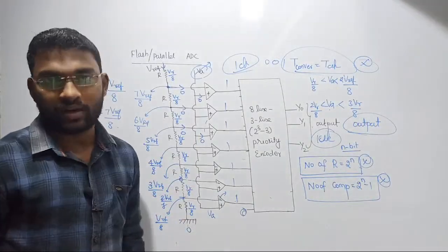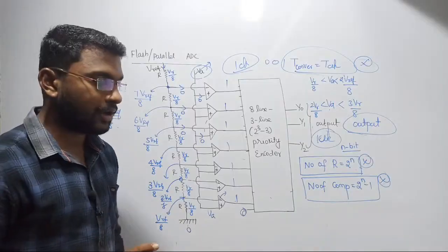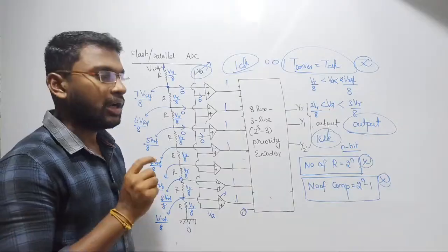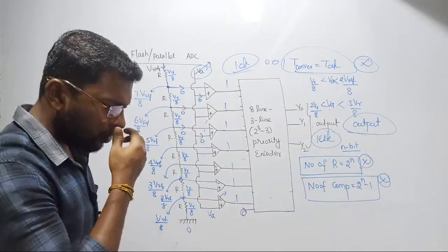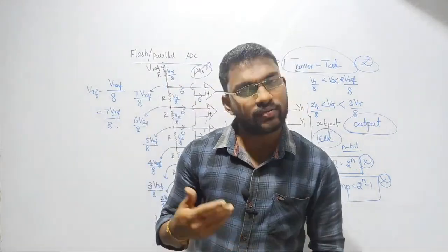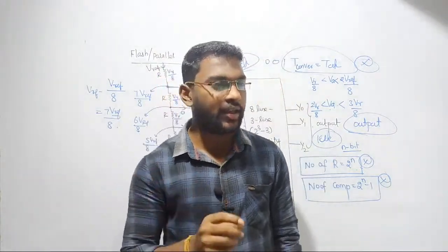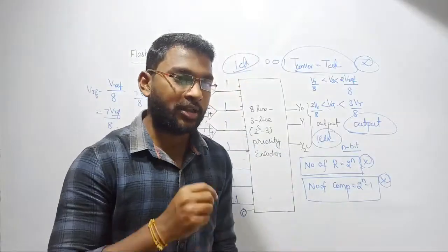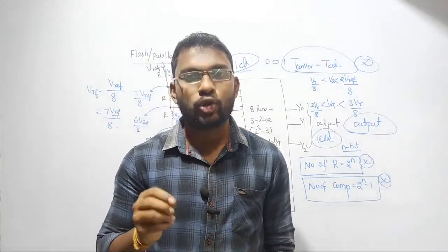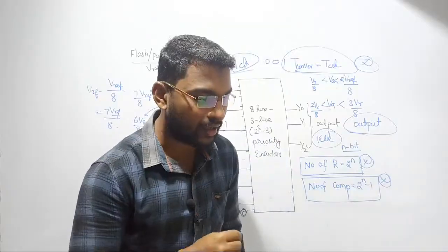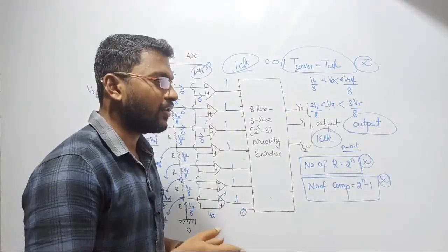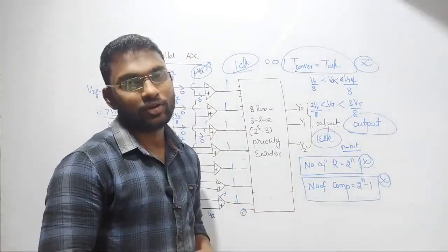That circuit itself we can observe, so it's over completely. So sample and holding circuit is not required for whom? Dual slope integrator. But we know in the dual slope integrator accuracy is very high. You can get the exact, accurate data. But the problem with the dual slope integrator is that it is the very slowest converter. We saw already yesterday when discussing speed of conversion, who is working very slow? Dual slope integrator only.